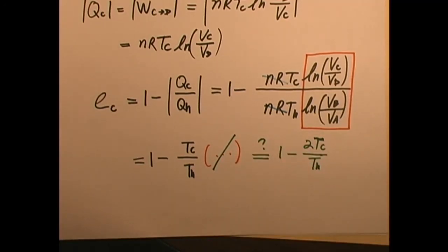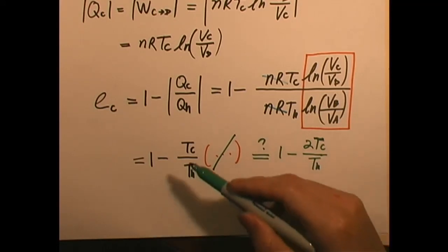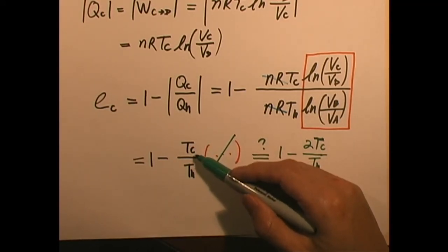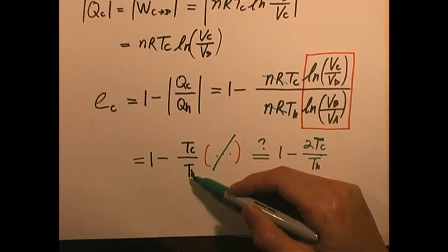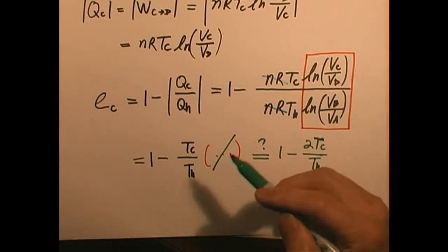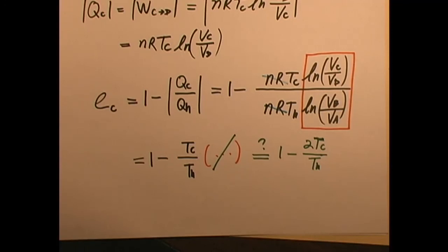So this really is just equal to 1. If it's 1, that's perfect. What that means is that when Tc equals Th, there is no temperature difference between these two reservoirs, and then the engine becomes useless. Because the reason why the engine works is because you extract heat from high temperatures, you dump part of it at low temperatures, whatever is left you do work. But when these two are the same temperature, you have lost this potential difference, if you will. So the engine becomes useless.